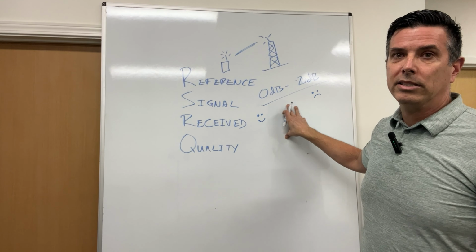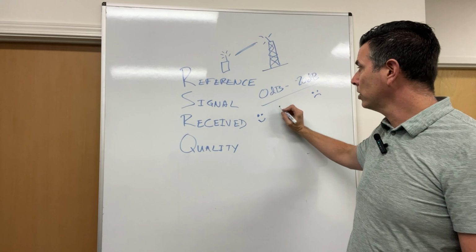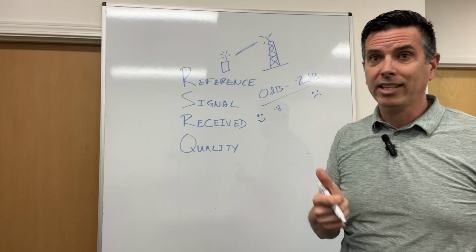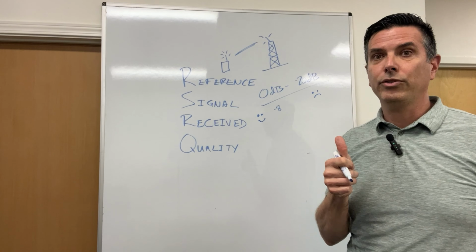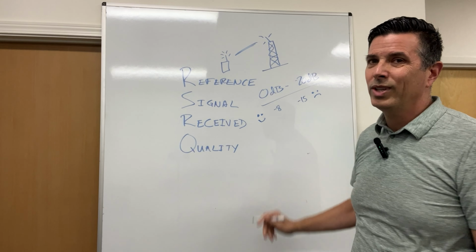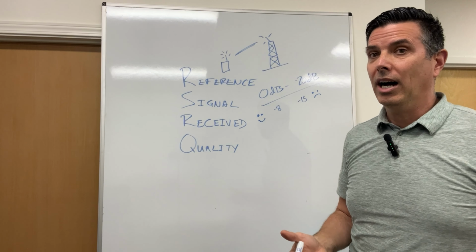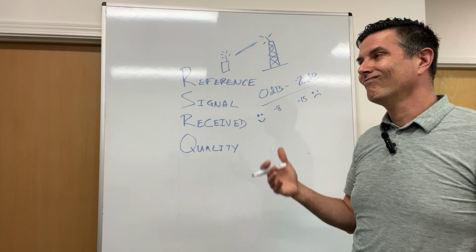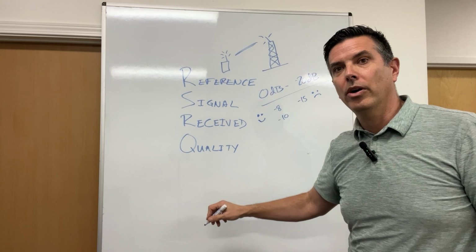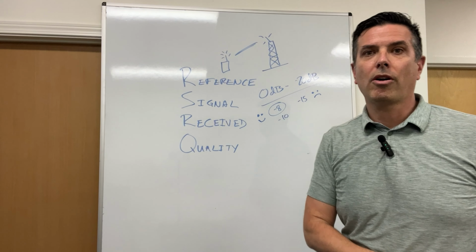What you commonly see in plots is around neg 8, neg 9 for a good signal. You know, if you have a neg 8 RSRQ, that's good. That's good quality link. That's going to give you good service. If you're neg 15 RSRQ, that's not too great. If you're neg 18, that's poor. You want to be, again, neg 10 down to 0. You want to get in the single digits for your RSRQ. You want to be neg 4, neg 5.